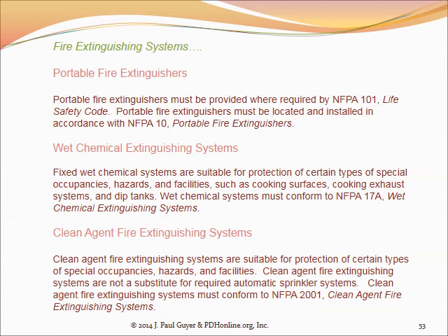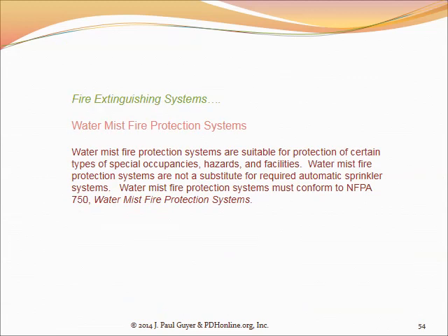And there are some other categories: wet chemical extinguishing systems and mist systems. The water mist systems are typically used maybe in a tank environment where you've got a liquid in a tank, or it could be a solid in a tank, and they lower the temperature within the tank sufficiently to below the ignition point of whatever is burning in the tank.